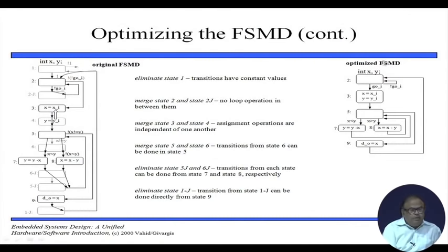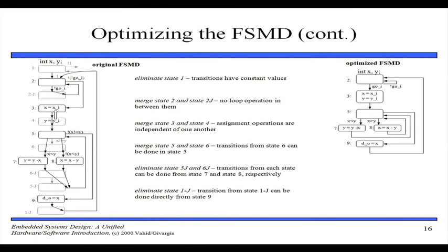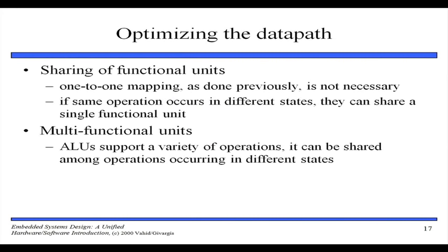For encoding the states. Now, since the number of states is less, the number of bits required is also less. Since there are 6 states, I can do that with 3 bits. So, I will be needing 3 flip flops, thereby I am optimizing. Not yet coming to the complexity of the control path, but purely on the number of flip flops. So, that is the second part of optimization that we can do.